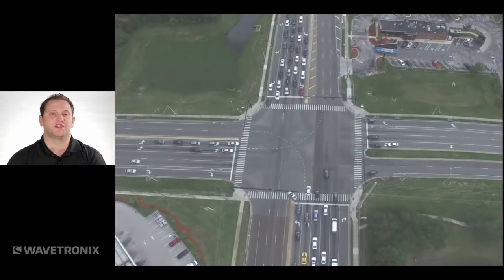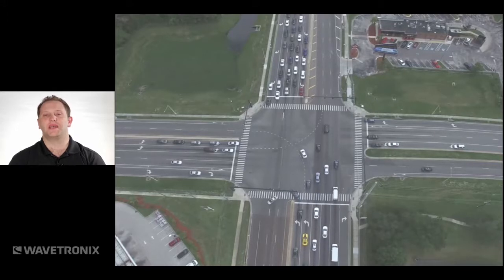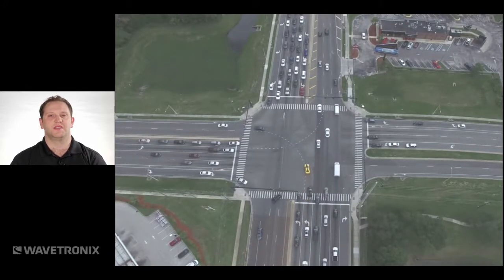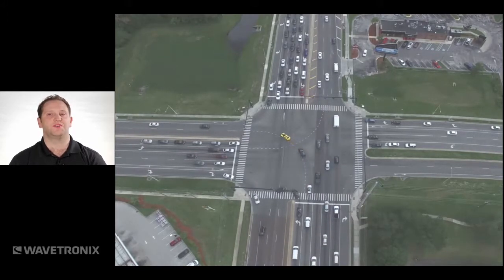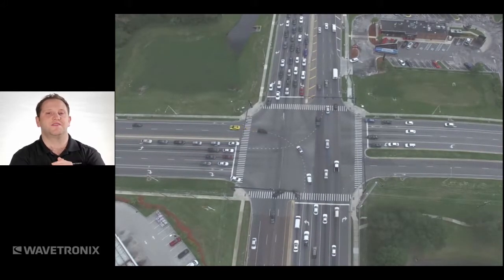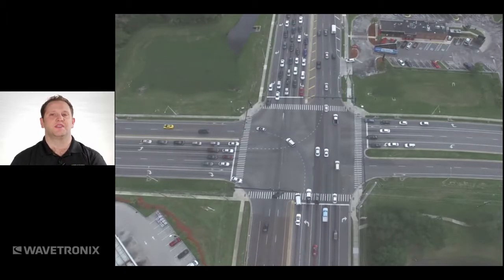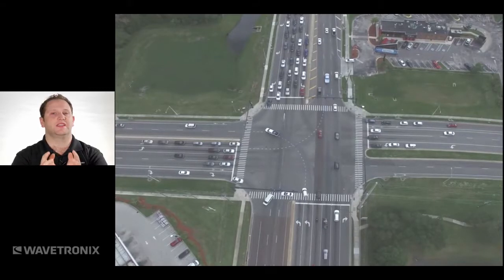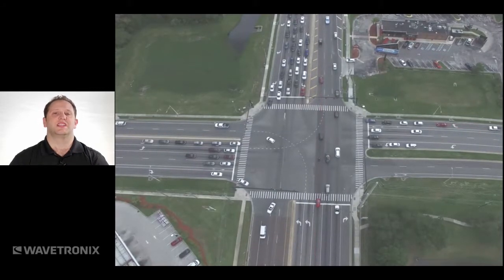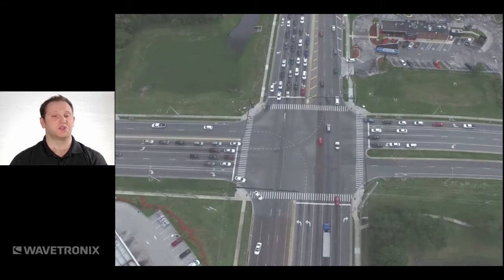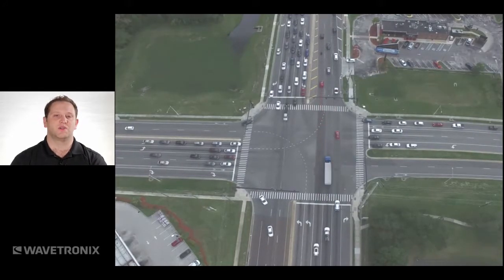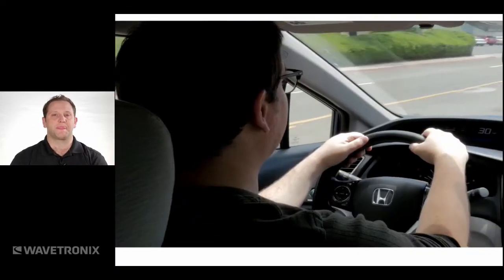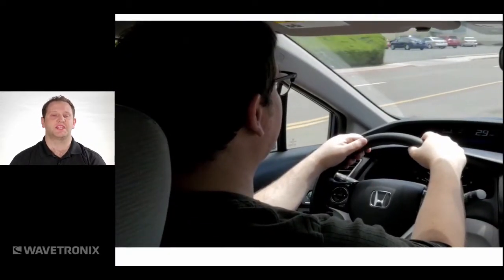But first, we're going to talk a little bit about passage time. The goal of passage time is, there are really 3 of them. The first one is to ensure queue clearance. The passage time should not be so small that the resulting maximum allowable headway causes the phase to have frequent premature gap outs. A premature gap out will leave a portion of that stopped queue unserved, and thereby lead to increased delays and possible queue spillback. So ensuring that the queue is clearing is one of the original important reasons why passage time came to be. The next one is to satisfy driver expectations.